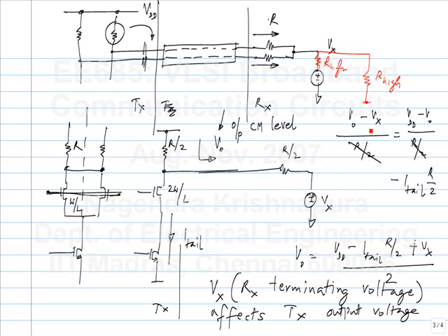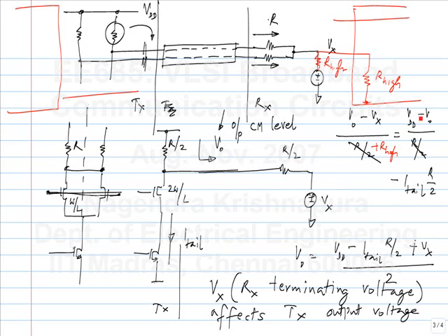Yeah, that's true. Essentially this is like you terminate it, but then the Vx will not significantly affect the output voltage if R high is much more than R. Is that clear? So here I took V0 minus Vx by R by 2. So here I should have to take R by 2 plus R high. Okay. So the weightage for Vx would become much smaller in that case. Yeah, that is one possibility.